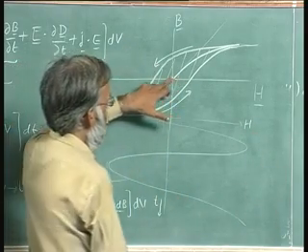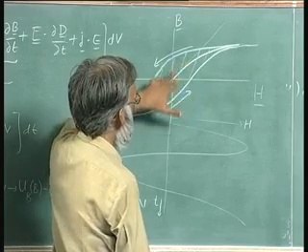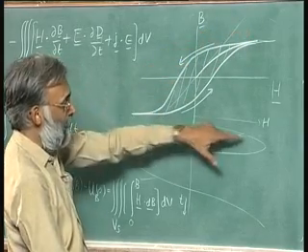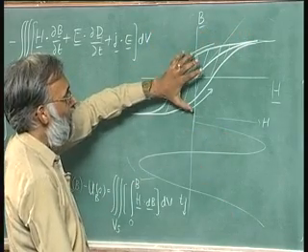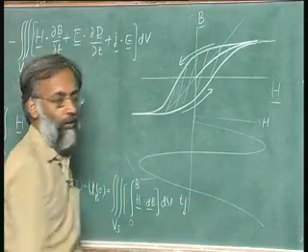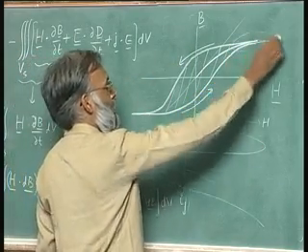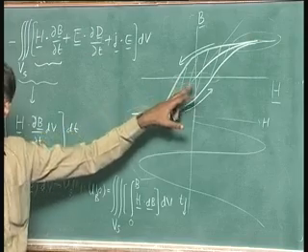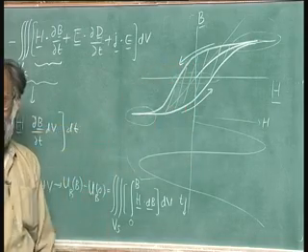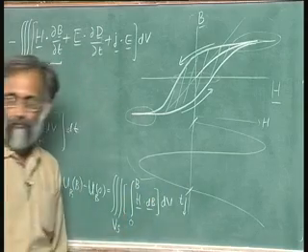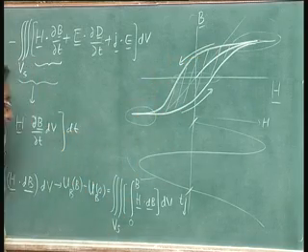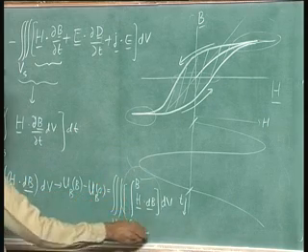then as H changed, the magnetic field would rise and saturate, then come down, saturate, come down, come up and saturate. So, as this cycle went on, you would get a magnetic field that did not look like H at all. In fact, it showed all these signatures of saturation as well as signatures of hysteresis. And you know very well that the energy dissipated in a single cycle is given by the area of this curve, B dH or H dB. That is where this concept comes from. This is the general form